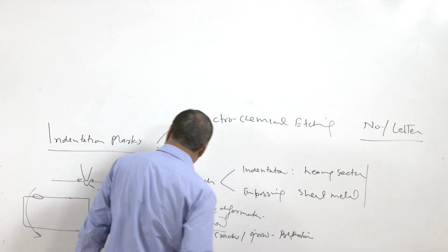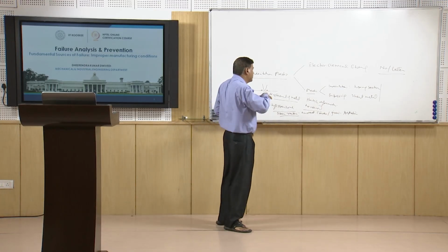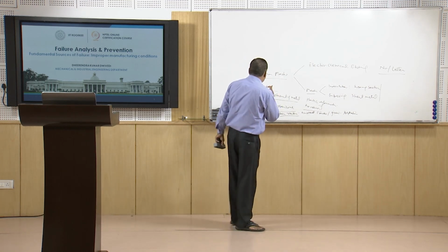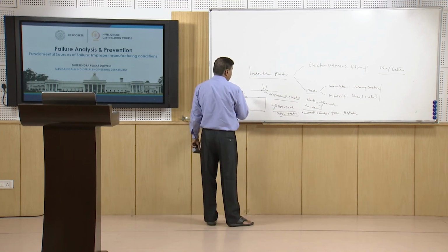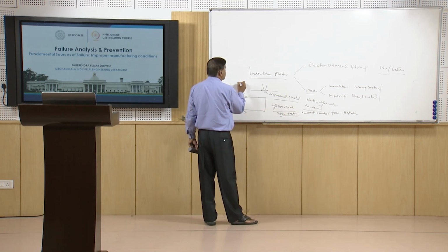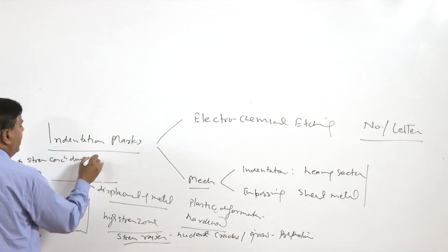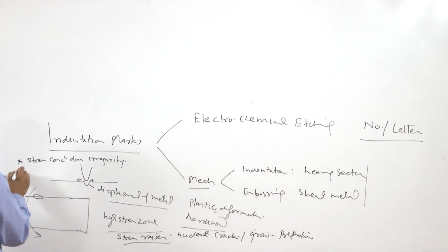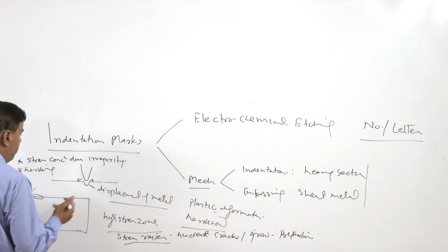So, mechanical indentation using punches sometimes hardens the metal, and at the same time it acts as a stress raiser, because an irregularity in cross section is created intentionally. There are two aspects involved. One is the stress concentration due to the irregularity being created, and the second is the hardening of the metal around the locations where the punching or indentation is applied for marking purposes.